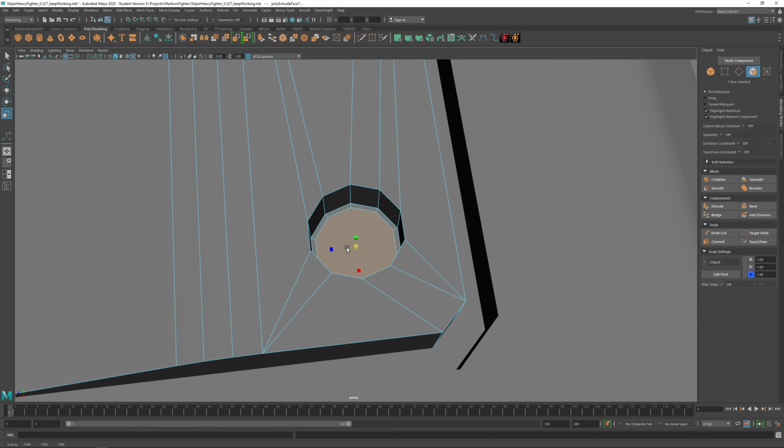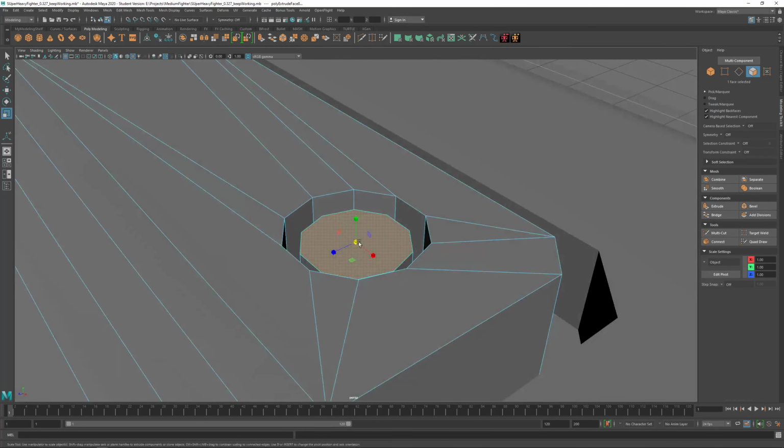So I extrude it a couple of times, move it up, extrude. I use R, so when you press R and you use shift, yeah, so I press R once and I'm in scale mode, and I hold shift, and you see what's happening is just extruding.